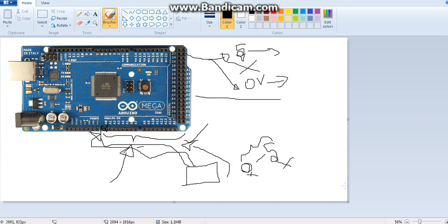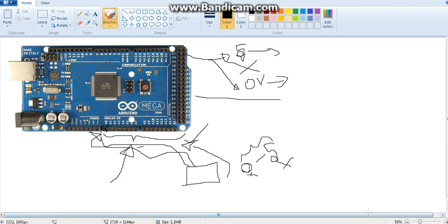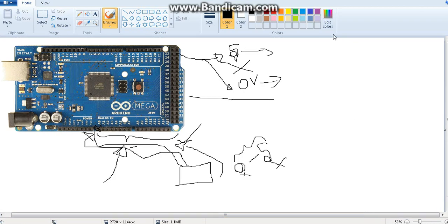I will make it a little bit big so that it is understandable. Let's say a source or sensor or a voltage source, anything that is capable of giving from 0 to 5 voltage. Any value in between it can give as an input, because it is analog. If it is a digital input source, it can give either 0 or 5, nothing else, no intermediate values. But it is an analog source, so it can give intermediate values.